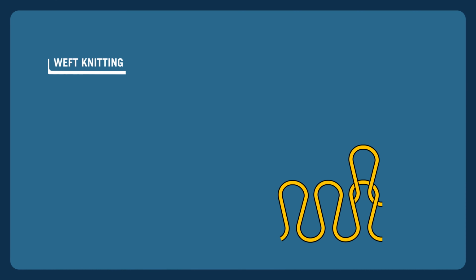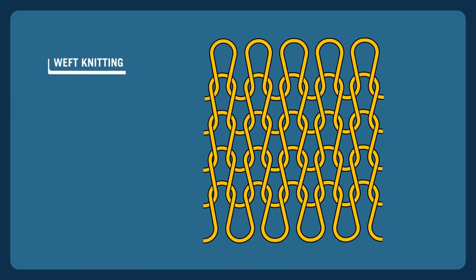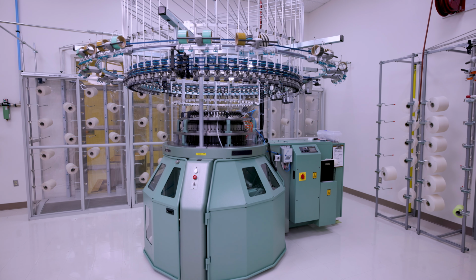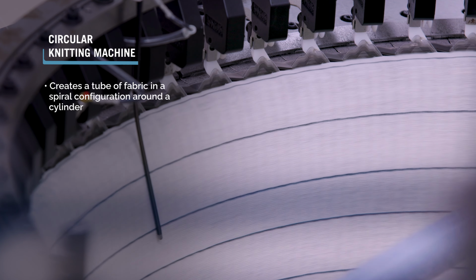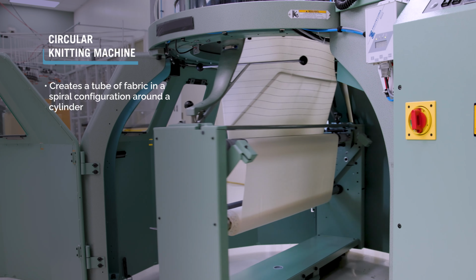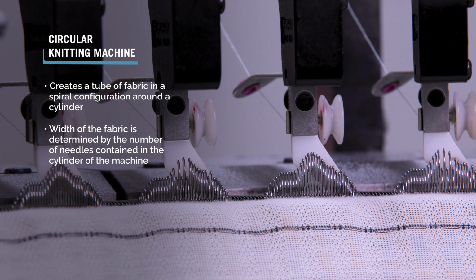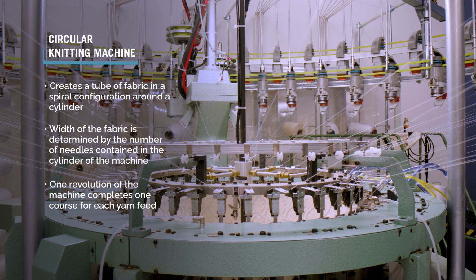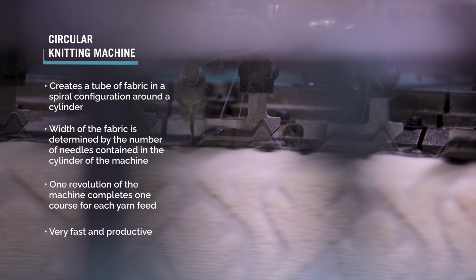Weft knitting is made of loops formed in a horizontal manner by adjacent needles. The most common machine used for weft knitting is the circular knitting machine. This machine creates a tube of fabric in a spiral configuration around a cylinder. The width of the fabric is determined by the number of needles contained in a cylinder of the machine. One revolution of the machine completes one course for each yarn feed. Circular machines tend to be very fast and productive.